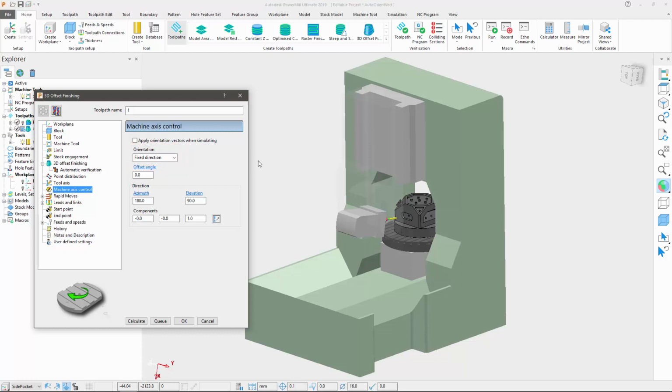These user-defined positions are, in many cases, impossible to achieve due to machine configuration and kinematics, and could lead to ambiguous orientation vectors or undesirable behaviors requested while simulating, such as a retract and reconfigure move. By default, orientation vectors were set to free, but these resulted in similar behaviors to those caused by setting an ambiguous one, and meant that the users, due to subtly different starting conditions, may have seen different results when simulating compared to the real behaviors observed on their machines.